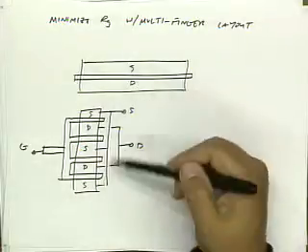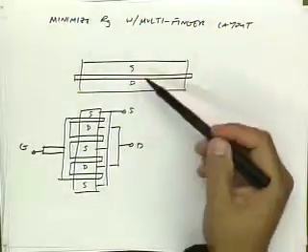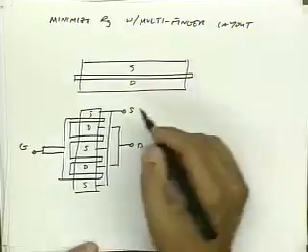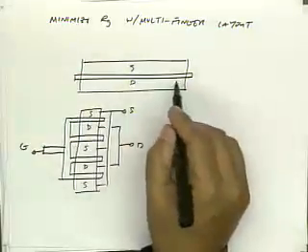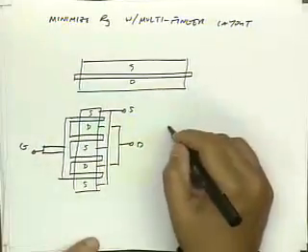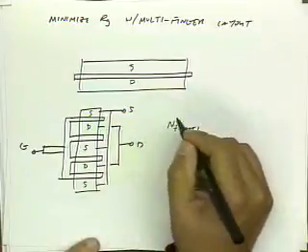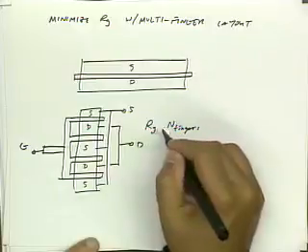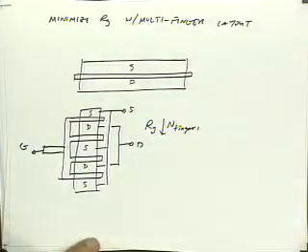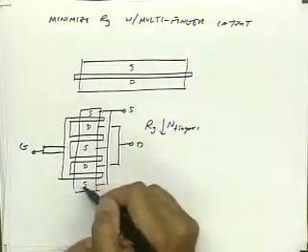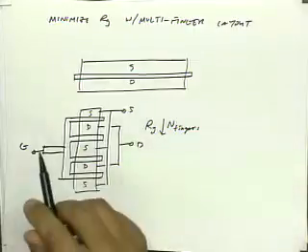And you can see this has a twofold improvement, because not only am I reducing my gate length by n, so if I have n fingers, our gate resistance goes down proportional to the number of fingers, but since these are now in parallel, I get another factor improvement.